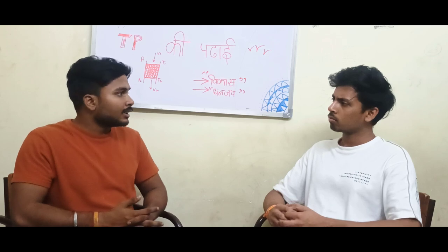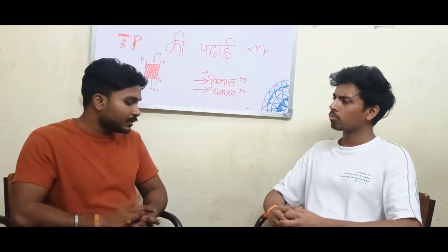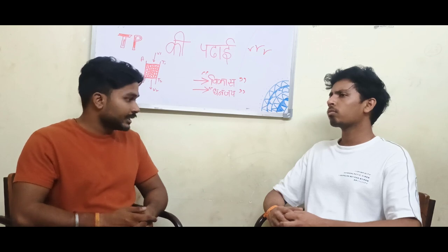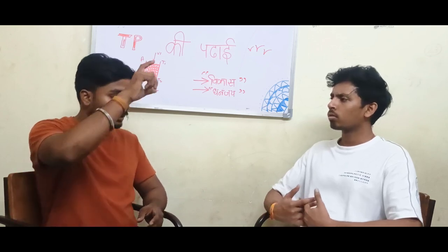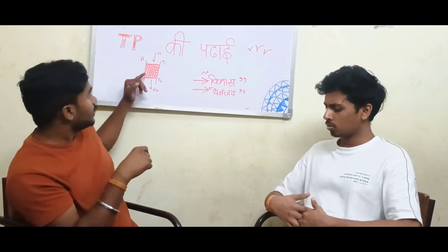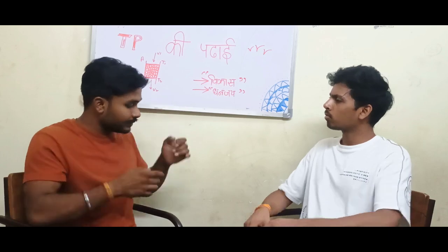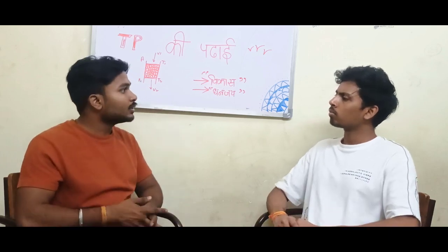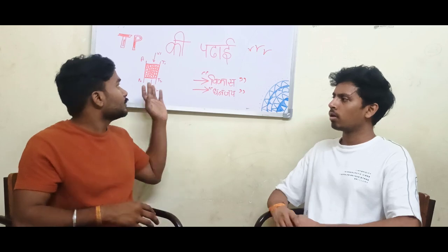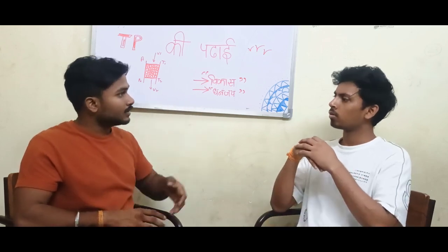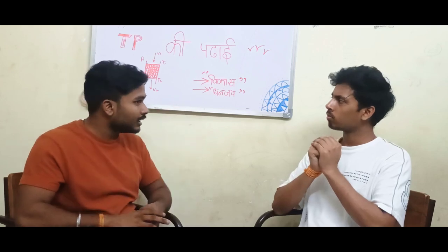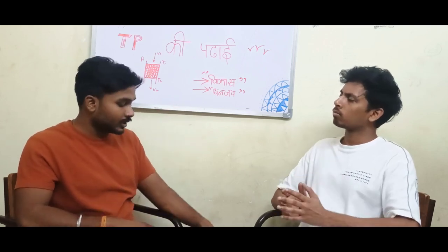For experimental determination of the mass transfer coefficient, there are techniques such as tracer techniques, where you measure the concentration profile along the column. You can use a step or pulse input method and observe the step response to get the experimental mass transfer coefficient.